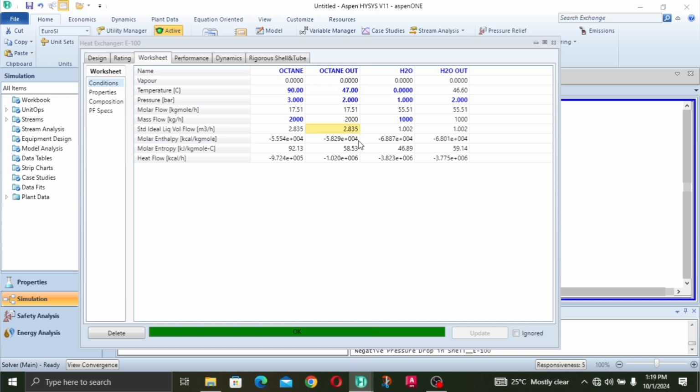And with this, we have successfully operated our heat exchanger using the mass flow rate factor to improve the rate of our heat transfer, thermal energy transfer. So remember, change in temperature and mass flow rate are majorly the two parameters which affect our heat transfer, our energy transfer from our sensible heat equation when we apply this in ASPEN HYSYS. The third factor is the specific heat capacity, but we're not using that. So with this, we have covered the second parameter from the equation.